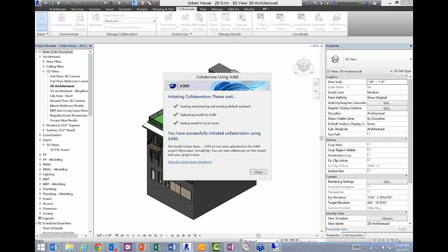You end up deleting a file called uistate.dat. So if you're out there on the web and you're trying to solve this, just Google search Collaboration for Revit uistate.dat. And the first hit's going to be our technical solution. I'm going to walk you through fixing it.